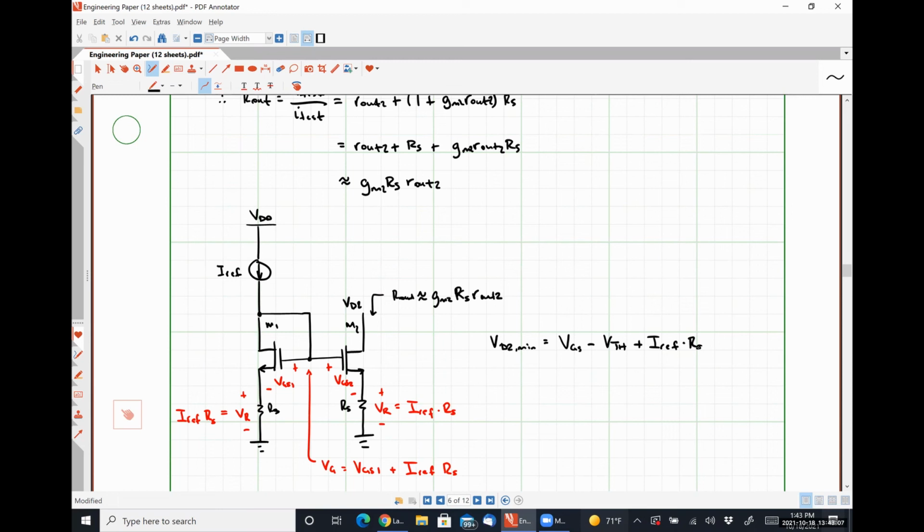So what we're going to talk about, I have 2 minutes left. So what we're going to talk about on Wednesday is ways to replicate this. So getting that same kind of output resistance increase by attaching stuff to the source but figuring out how we can minimize the effects of the trade-off and losing headroom. All right.